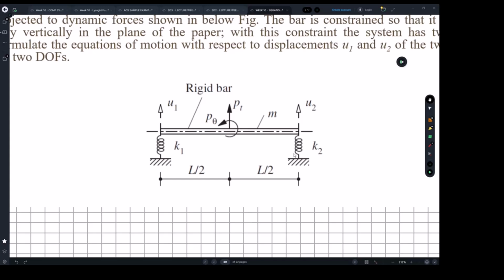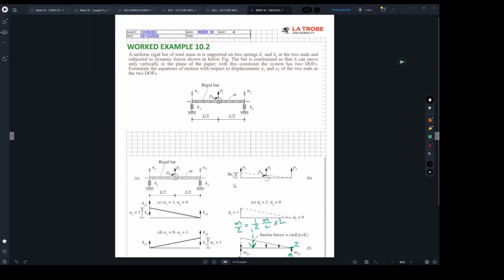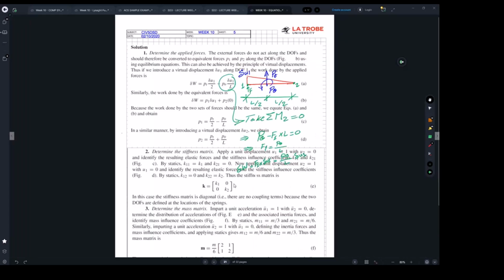For example, if you've got a generator or an MRI unit in a hospital sitting on a special slab, the key thing they're going to ask dynamic engineers to check is, is it safe? Can the slab take the vibration without a problem? And that's what we're doing. We all know we have to go and find the natural frequency. But once you find it, you can then assess it and find out whether it's close to the forcing frequency of the equipment or not, and make a decision.